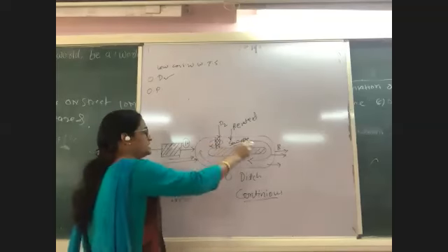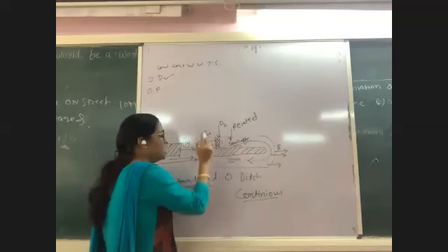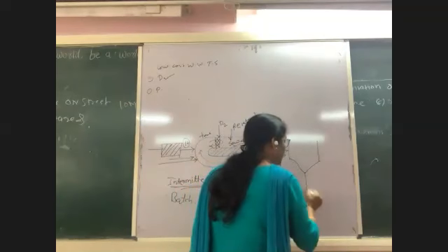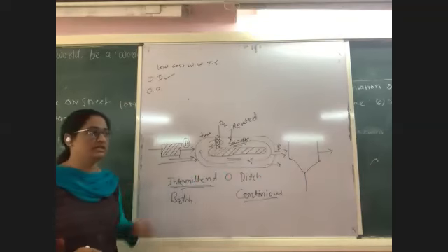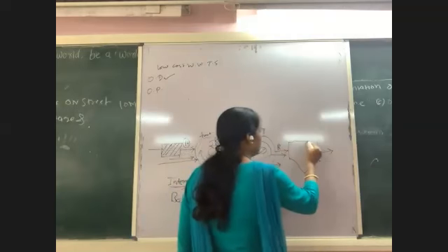The aeration will be performed in this tank, and for sedimentation purposes, we will provide a separate secondary clarifier. A simple design we can construct, and we can allow the sludge to settle in the secondary clarifier.